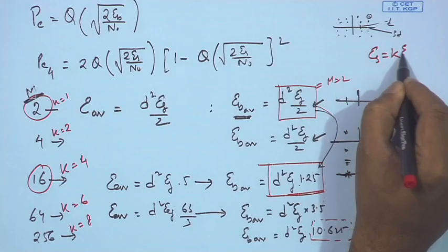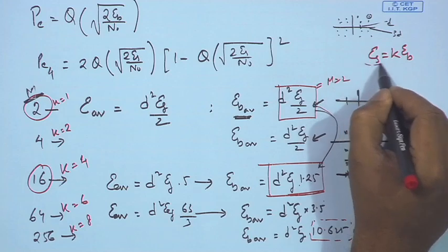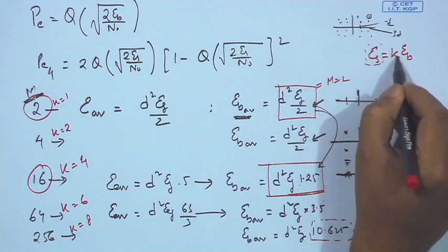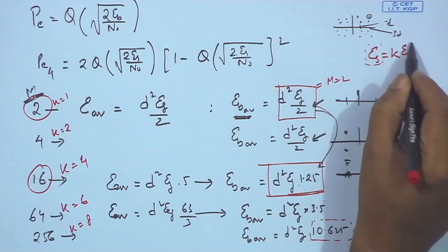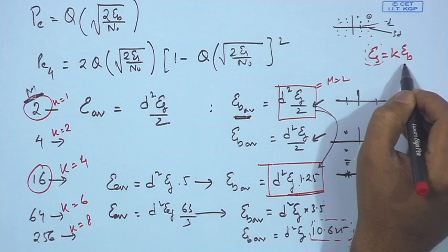Now, it is not necessary over here to repeat the similar things for M-ary orthogonal signals, because we have already shown that if you keep the energy per symbol the same and you have the relationship Es equals k times Eb. So, in case of M-ary orthogonal, if I keep the same constant Es and keep increasing k, Eb goes down. So, in that case the energy required per bit goes down. We have been saying this thing.